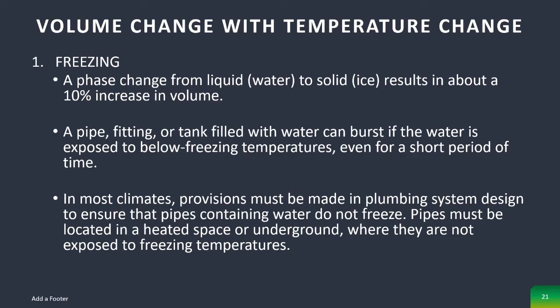In most climates, provisions must be made in plumbing system design to ensure that pipes containing water do not freeze. Pipes must be located in a heated space or underground where they are not exposed to freezing temperatures.